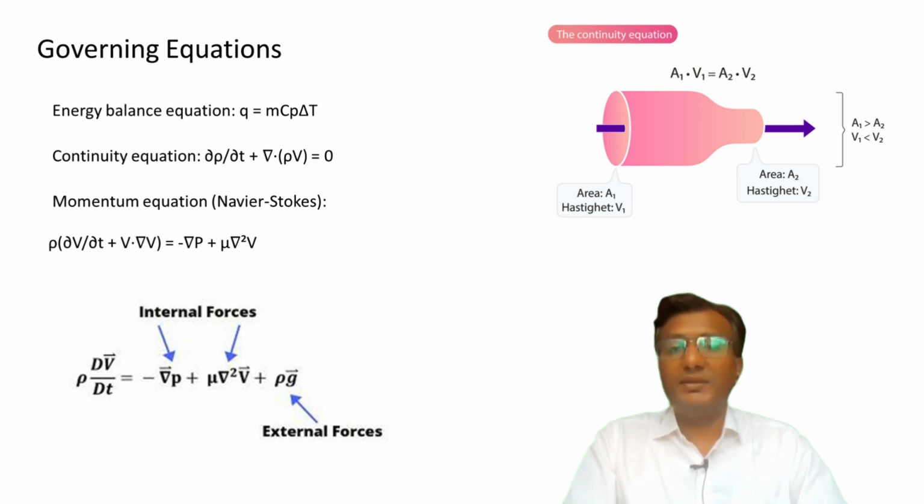As we all know, the Nusselt number is a function of the Reynolds number and the Prandtl number, so it allows us to correlate the flow conditions with the heat transfer. For example, in a heat exchanger, a high Reynolds number indicates a turbulent flow, which increases the value of the Nusselt number and the heat transfer coefficient h. These numbers simplify complex convection problems, guiding the design of efficient systems like radiators or cooling fans. So let's apply this to the heat transfer over a flat plate in the next slide.